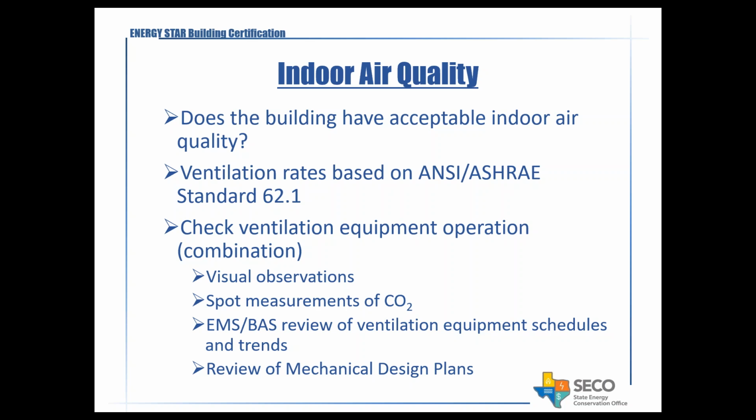That could be visual observations of the ventilation equipment in operation. What's the status, and how is it operating? Is it operating while the facility is occupied to pull in fresh air? We can spot measure CO2 in different occupied spaces. We can use the EMS or the BAS system to review the ventilation equipment schedules and operating trends. We can look at past data throughout the weeks, or going forward as well, what the schedules are. And then we can also review mechanical design plans.